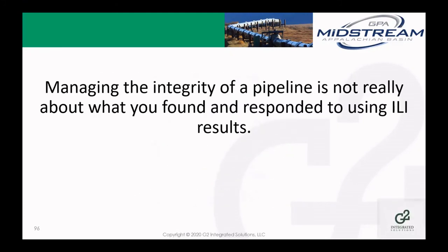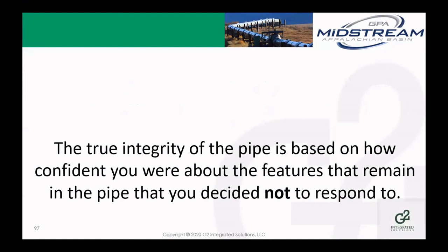And you have to keep in mind that the true integrity of a pipeline is not really about what you found, what the tool detected. The true integrity of the pipeline is based on how confident you are that everything was detected, that everything that you decided not to verify is okay staying in your pipeline.